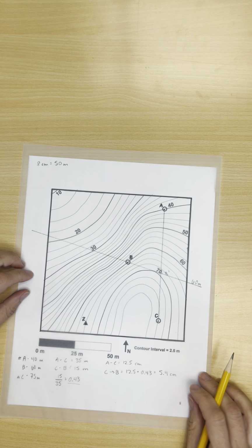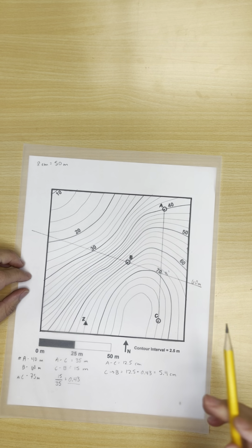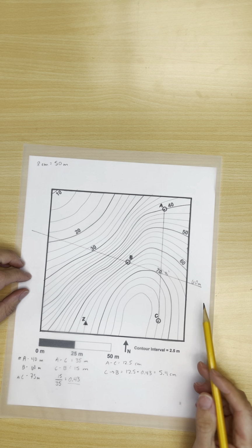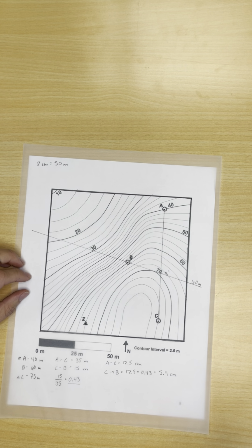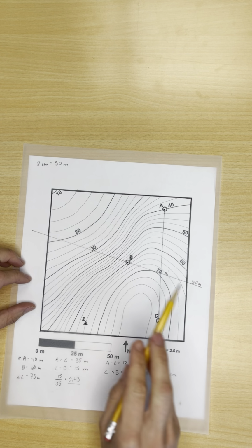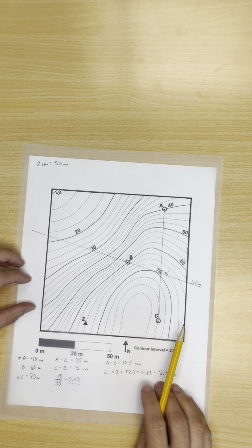Because this is a structural contour, it is a strike line, we can just use this to determine the strike of this bed, right? All we need to do is measure with our protractor the angle of that line with respect to north. The first thing that we need to do, because we could measure two different directions here, is we need to figure out our dip direction.